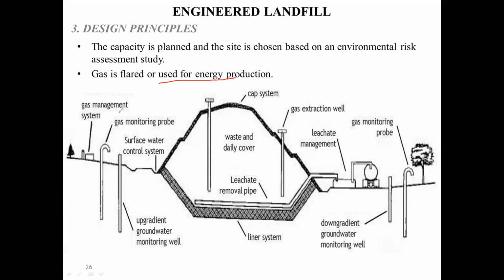Then we have a gas management system. We have to design the gas management system, which analyzes the amount of gas which is going to be generated, and based upon this, what the methods are, which different gases are to be taken for energy extraction, and of the given gases how much should be extracted and how much should be flared. That we design. Then we also have gas monitoring probes. Gas monitoring probes keep a record, or keep an idea, of how many gases are being generated, and how the contamination of this gas is leading into the ground surfaces.